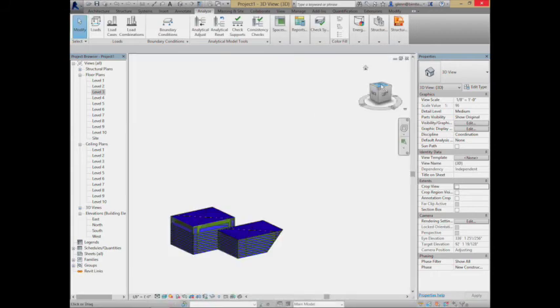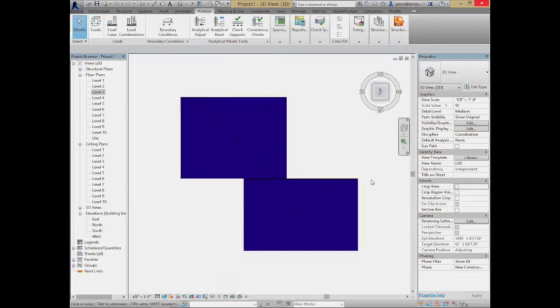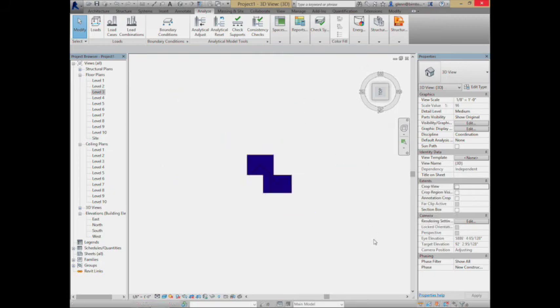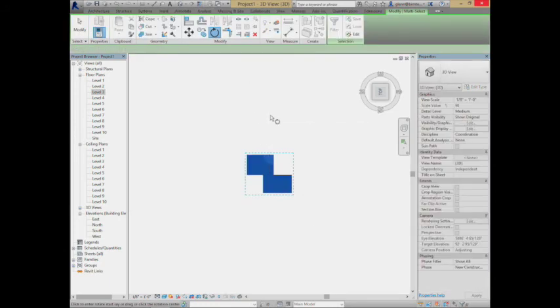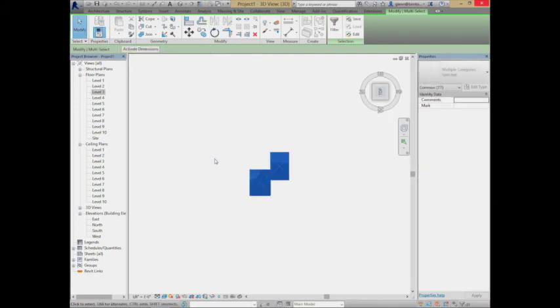So for example, right now, I guess that's the south side over here, the ratcheted side. If I wanted to try just orbiting this around, I could rotate the building and rerun the energy analysis to try a different orientation.